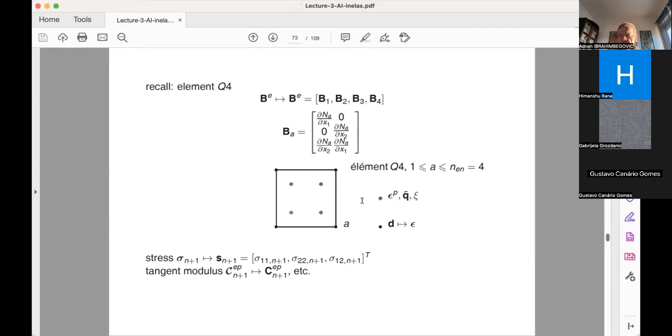Now, on top of this computation, I have to keep the values of the plastic deformation, hardening, or psi. We also use the Q, which is, you'll see, the backstress, if you have kinematic hardening. We'll get to that in a second. And all these values have to be stored for each and every one of these points. So you have to have access in your memory to the values that are stored there, which could be handled over the typical time step.